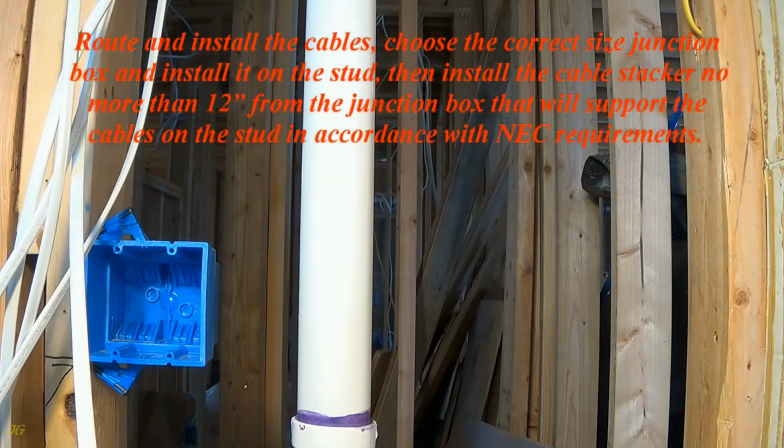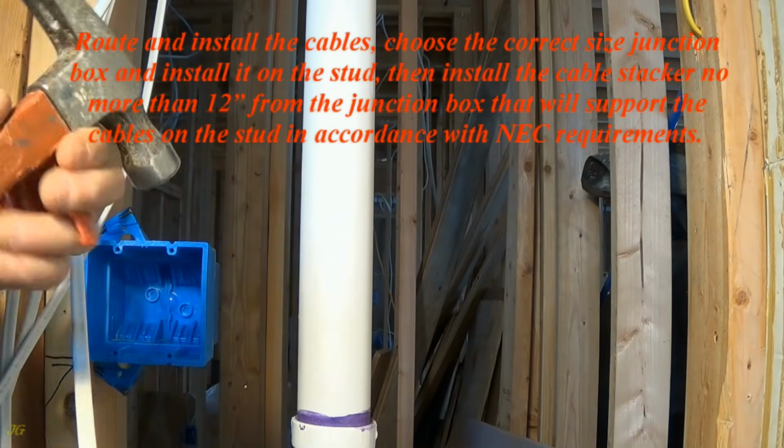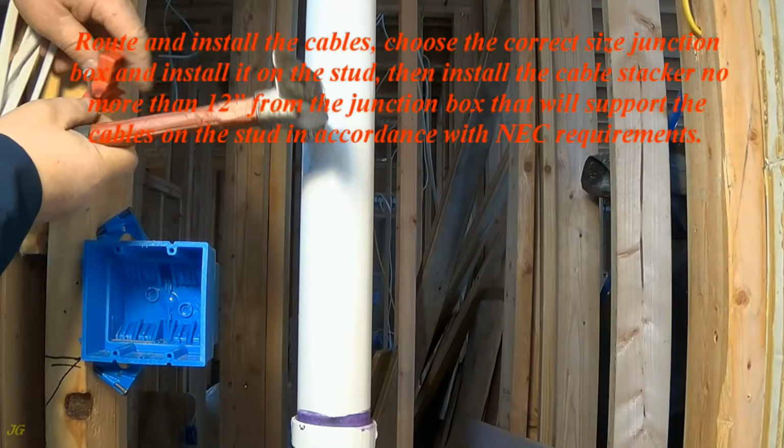Route and install the cables. Choose the correct size junction box and install it on the stud.